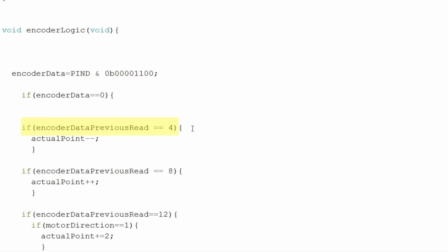The motor should fight to correct the position and return the encoder to the previous state. If a manual movement of the drive and encoder wheel results in the motor picking up speed and running in the direction the encoder was turned until it trips an out-of-bounds error, stops and flashes, you know the motor or H-bridge is wired backwards. When the step of the encoder is detected, the value stored in the actual point variable is changed to reflect the movement.